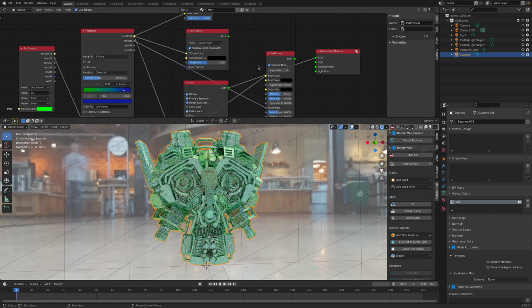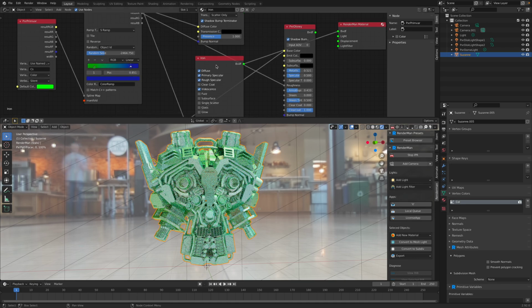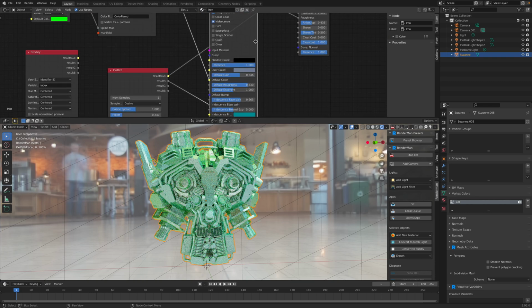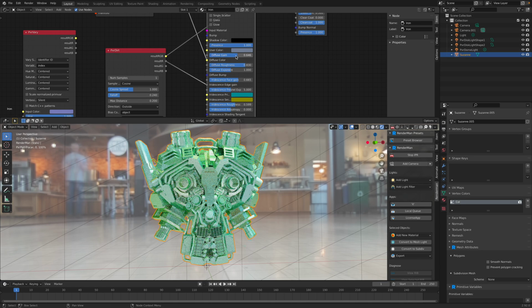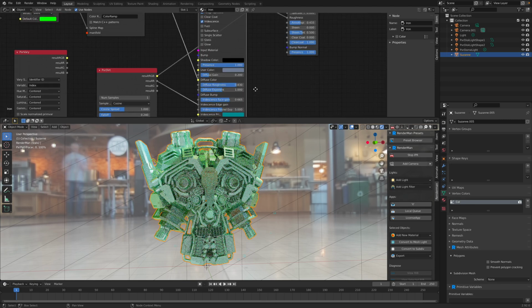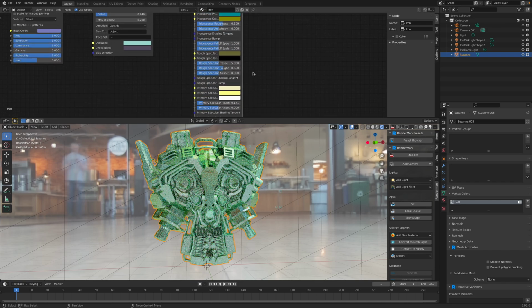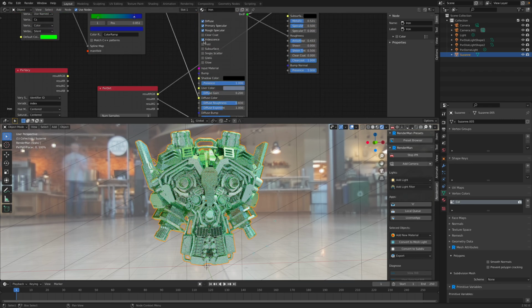Pixar Disney is a legacy shader. It's still convenient to use, but I think RenderMan works nicely with the Pixar shader. So this is the Pixar shader, set to a material that's a little bit metallic. Maybe this is too strong in terms of diffuse for metal, because a metal shader doesn't have much diffuse; I should give it more primary specular and rough specularity, which is down there. But here I'm using a lot of iridescence. Let me turn off that iridescence. Now it's becoming a little more metallic.